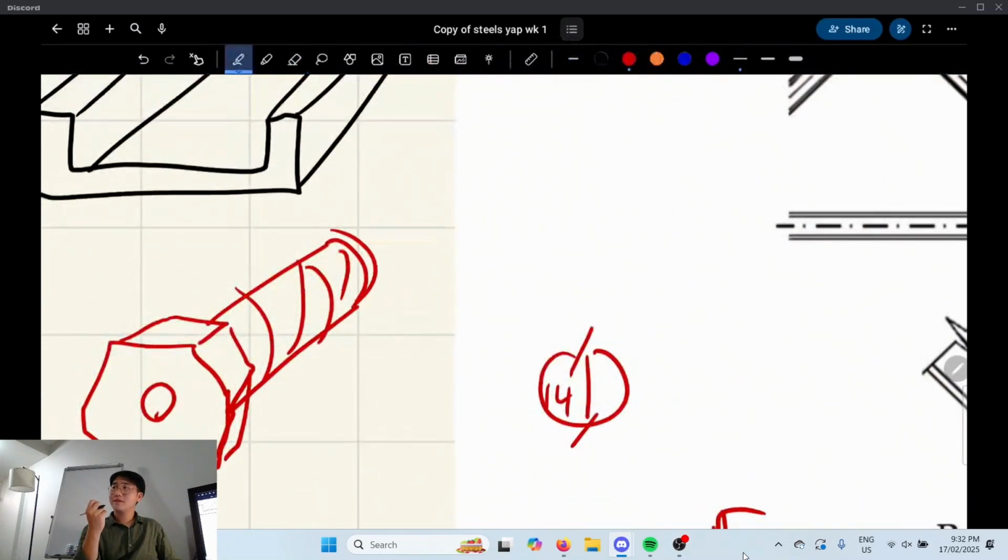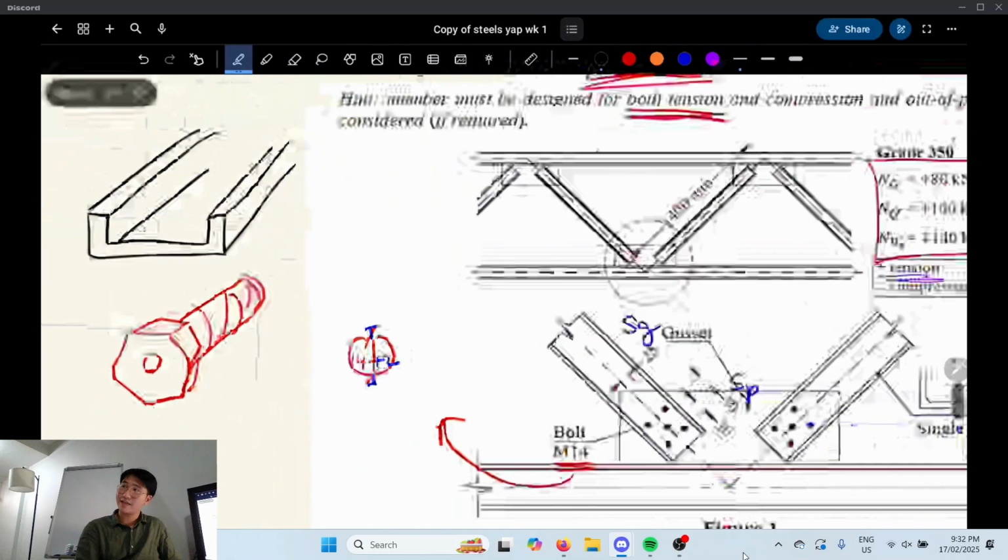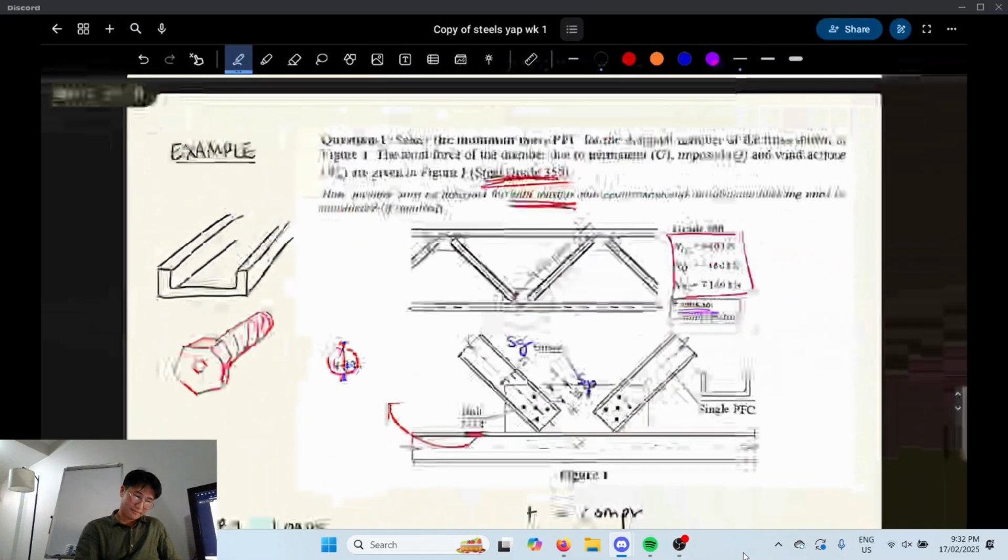It's called the core and I think the thread diameter. What do you think roughly that difference is? 1 or 2. Exactly. So you add on 1 mil on either side. So you just do +2. Whatever M bolt it is, you just add 2. That's the design safety.